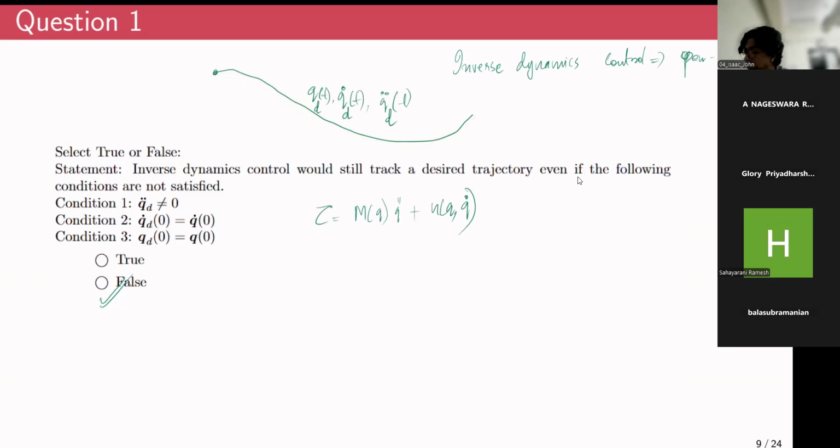So what you do for this open loop control is you would simply plug these trajectory variables, position, velocity, and acceleration, into this dynamic equation of motion. And then from here, you will obtain this control vector, the torque. Whatever you obtain from this control input, you supply to the robot manipulator.